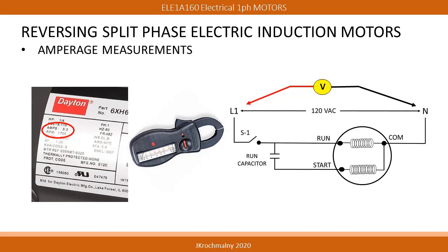Because of the higher amperages and possible shock injury, clamp-on amp meters are used. These types of meters are positioned so that the conductor is within the jaws of the meter. The meter jaws measure the flux lines generated in that conductor as a result of the amperage and correspond to an amperage scale.